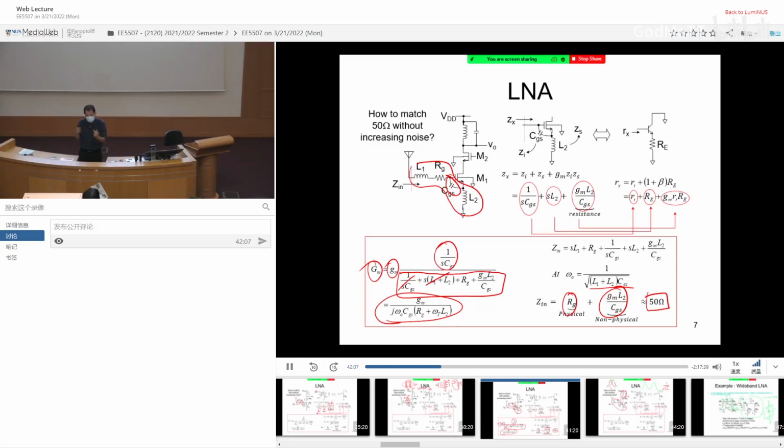What if I create an antenna that can take in 2.4 gig and 5 gig? I create one wideband low noise amplifier that covers 2.4 gig and 5 gig. So it doesn't matter whether it is 2.4 or 5 gig, I receive everything. Okay? So narrow band amplifiers have their limitation.